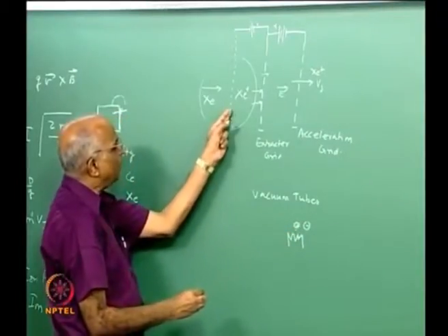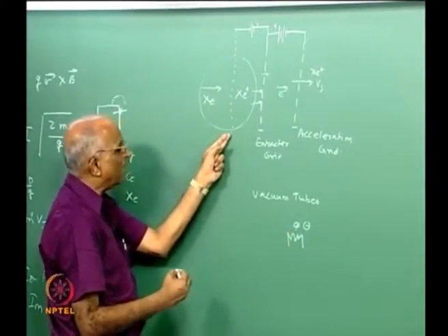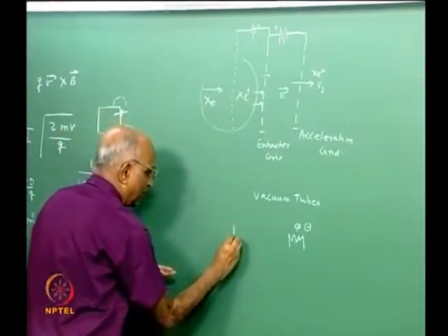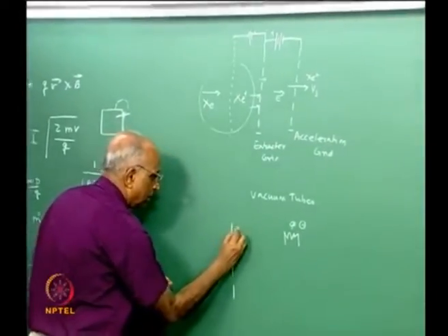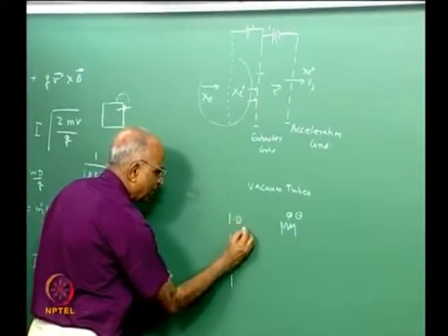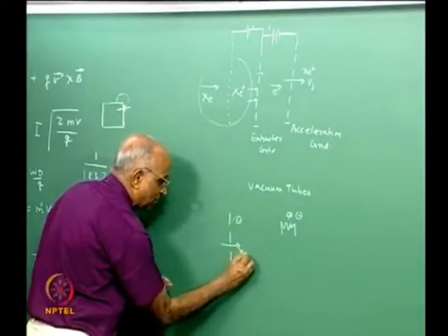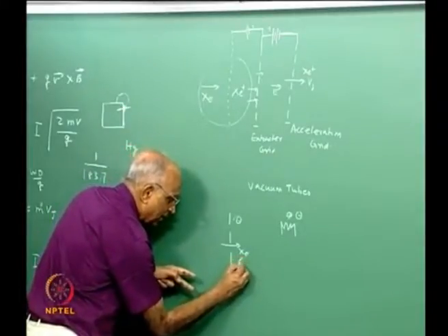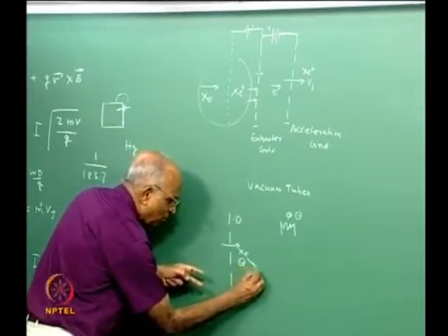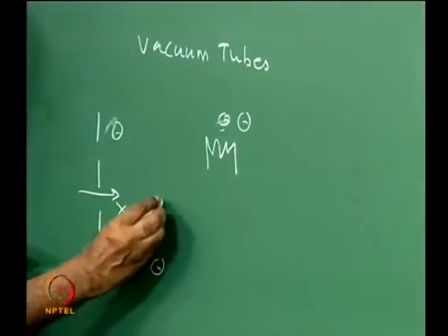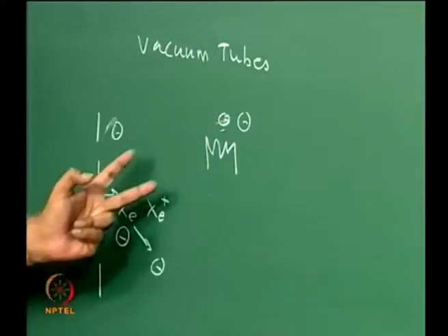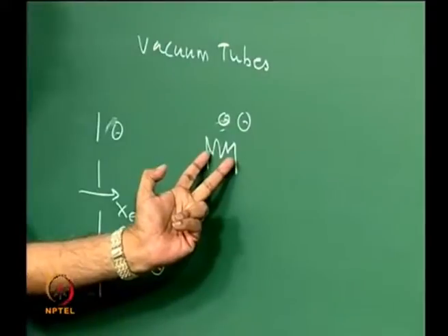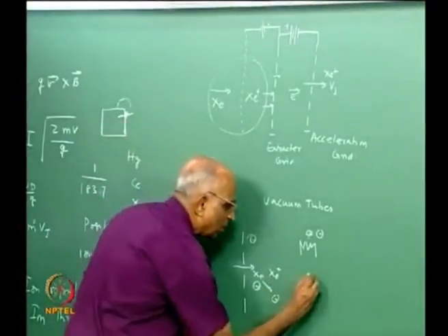Therefore if I could have a grid made of tungsten or even molybdenum for that matter, and I heat this particular grid, maybe electrons are generated from this grid, and these negative charges, when they hit against the flow of xenon gas which I am passing over here, the neutral xenon atom is hit by a negative charge, and this fellow knocks off one more electron over here, makes the xenon positive, and this is how I could create it using a sort of a resistor which is heated, which I call something like thermionic emission.